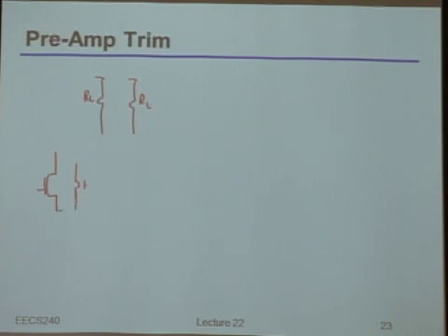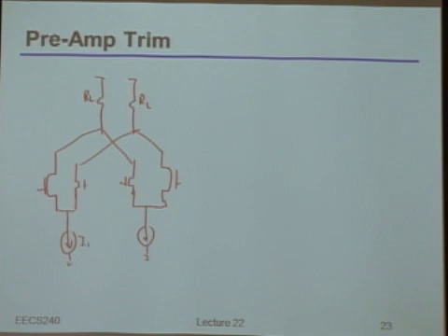What I'm basically going to do is, instead of building my differential pair the normal way, I'm going to split it into smaller pieces. In particular, I'm going to build two differential pairs, and this time around, I didn't just have a bad drawing. I intentionally drew these transistors in a weird way. In each of those differential pairs, I'm going to have one of the transistors be really big and the other one be really small. But I'm going to have two of these things.